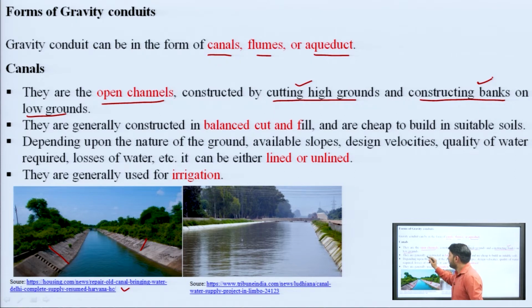So, what will be the best? They are generally constructed in a balanced cut and fill, means there should be equal proportions of cutting and filling, and that will result in an economical canal.